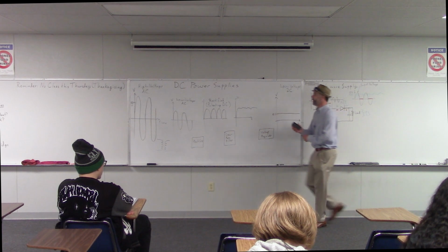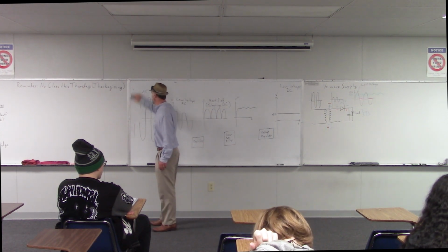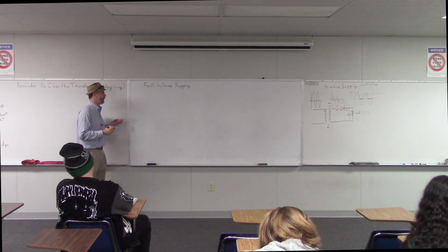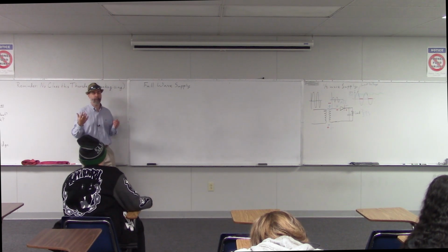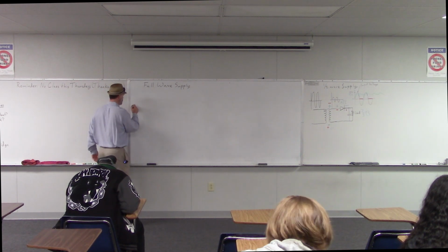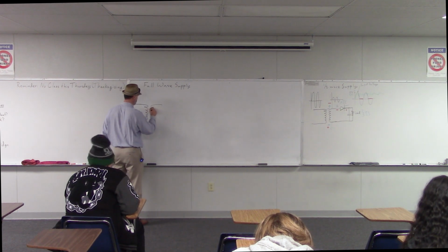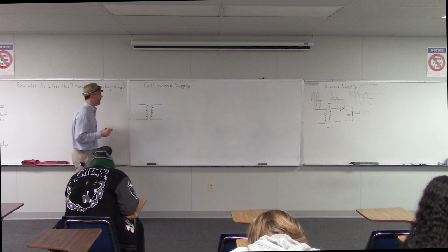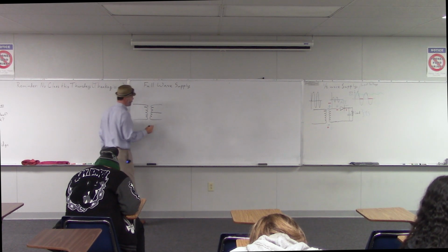All right. So then let's talk about the next type of power supply, which is a full-wave power supply. The first part of the full-wave supply takes the high-voltage AC and turns it into low-voltage AC. So what's that again? What component would that be? Transformer. A transformer, exactly. So we have a transformer here. And for the full-wave supply, we use a center tap transformer. And we'll see why in just a minute.